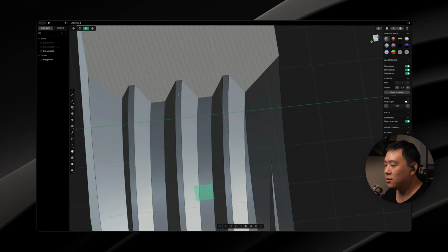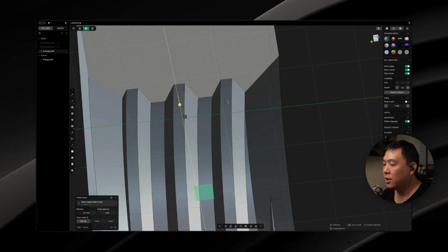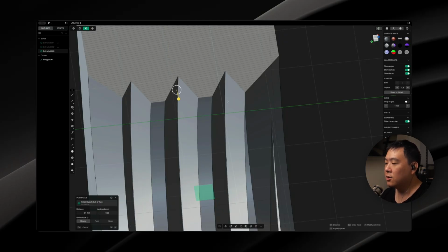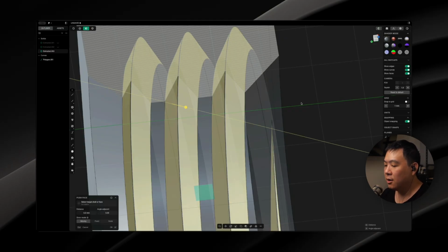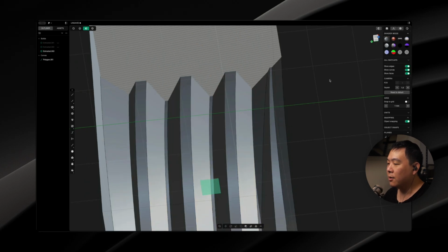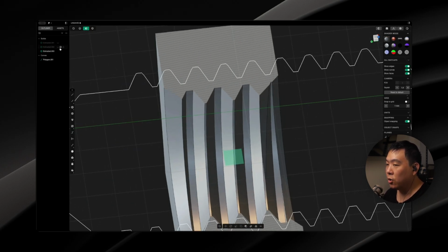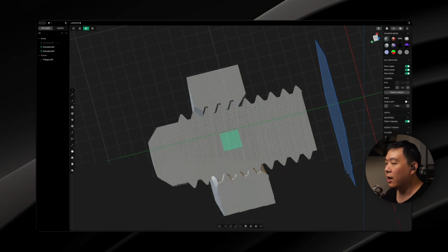I'm going to select this face over here and press D, enter in 0.1. Again going in the wrong direction, I'll put negative, and then enter twice to confirm. And then similarly, I'm going to select these two faces, D, 0.1, negative, and now we've widened everything up. So if we now show the bolt again, we've added some space to allow the bolt through.